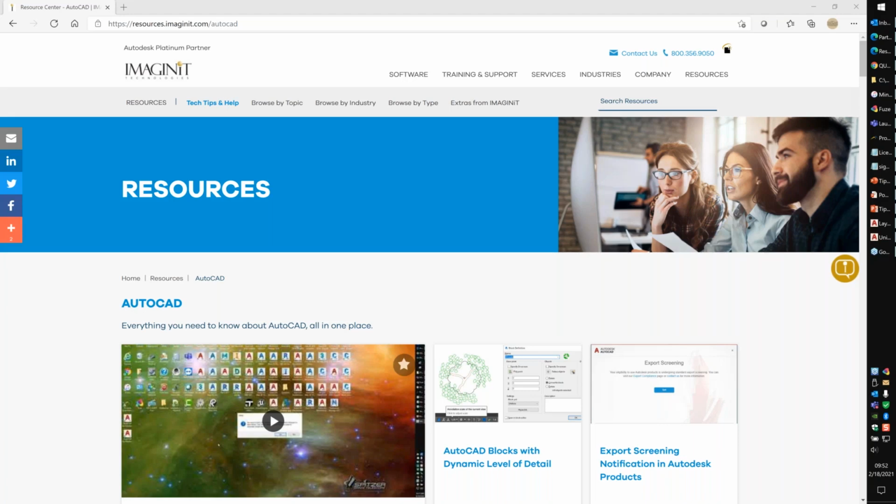Sometimes my viewports disappear and I can't find them. What could be causing that issue? Well, Jay, that's going to depend on a number of things. What layer your viewport's actually drawn on. Sometimes it's a corruption inside of your layouts. In some cases, I have a little script that I wrote in VBA that actually will return the visibility state to the viewport frames. So that's one of the things that we can talk about. Second, the request for instruction on paper space versus model space. Okay, that might be an excellent webinar for later.